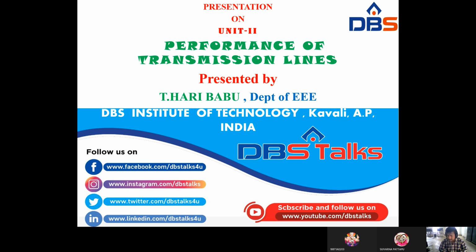That's why for the phasor diagram also, we take the reference as the receiving end voltage, and current IR is lagging VR by some angle. After that, the IR R drop and IR XL drop are added to VR. That means VR plus IR R plus IR XL is the sending end voltage.